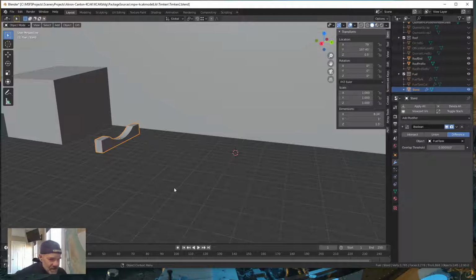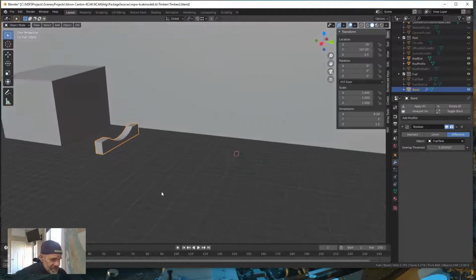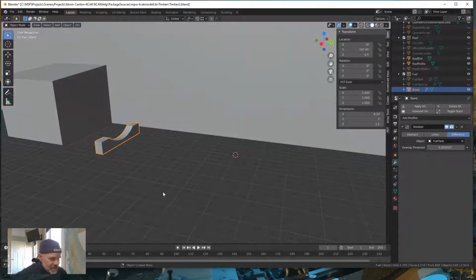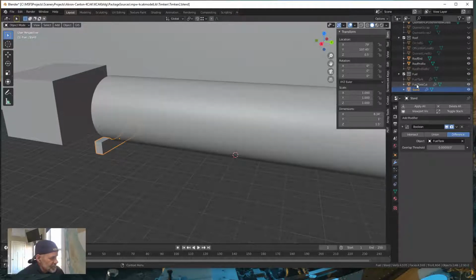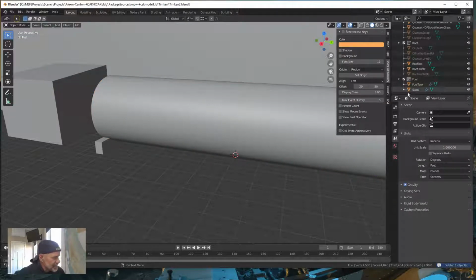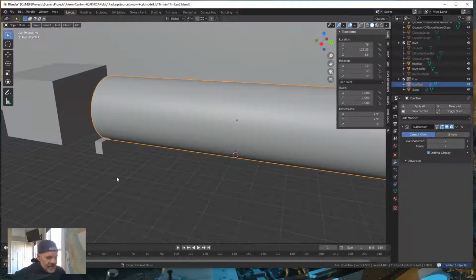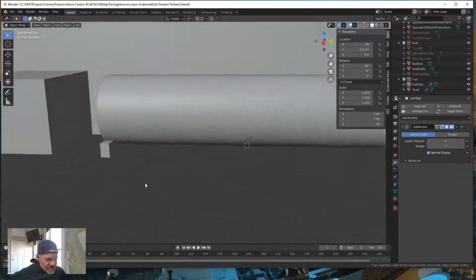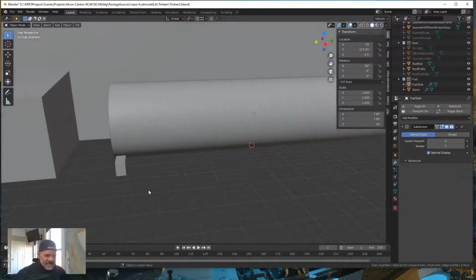The reason I make a copy is because I have that Boolean add-on. Old habits die hard, so you don't really need to do the fuel tank cut. We can turn our fuel tank on, and go ahead and delete the fuel tank cut, because the native Boolean operation doesn't do it.